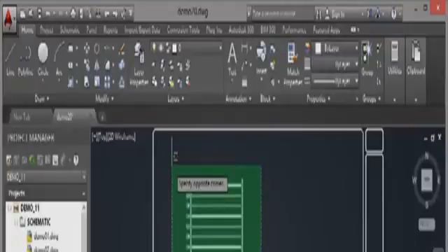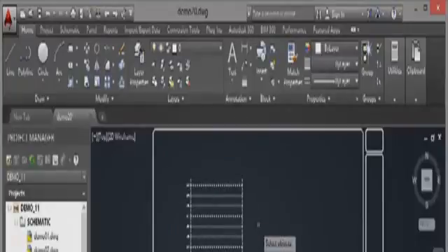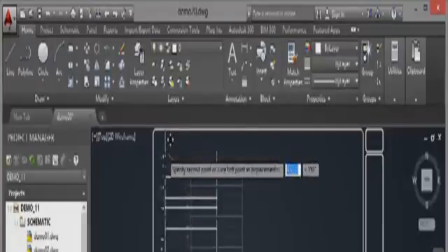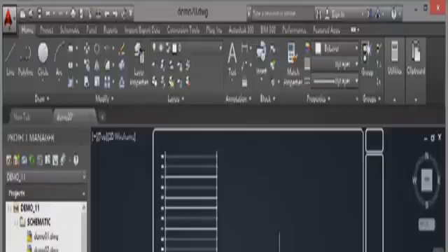So make sure you get everything first time. Click like so, and then in this case, because you've used the move command on the actual ribbon itself, you have to press enter to confirm. Over here to the endpoint again, get the endpoint snap, click, just drag it to where you want it to go, click again, and you've moved your entire ladder. That is the quickest and easiest way to move a ladder.